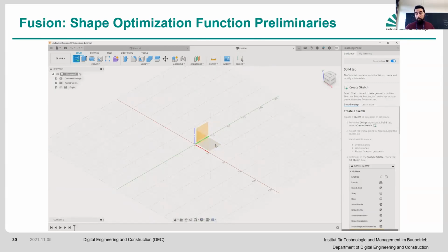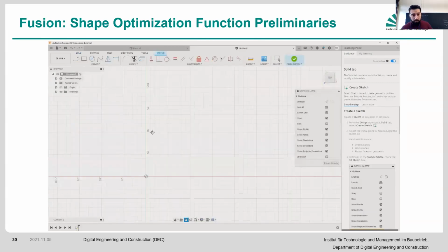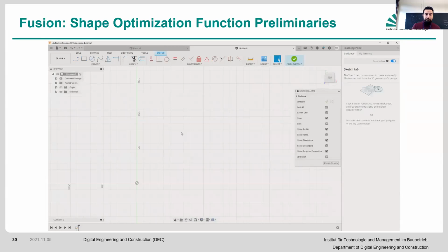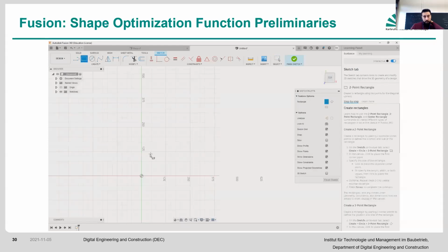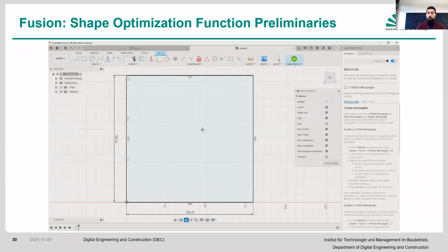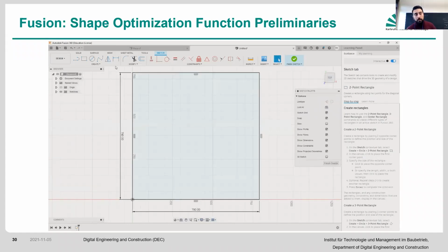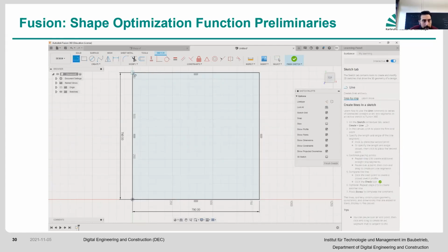First you have to identify which plane you want to start from. So we start from that plane. We again go through a particular rectangle, and we select that rectangle. Then from the origin, the dimensions were 790 by 790 millimeters, right? Again, you can change those units in the tools section here in Inventor if you really want to, but it starts with millimeters, so let's keep it like that as well.